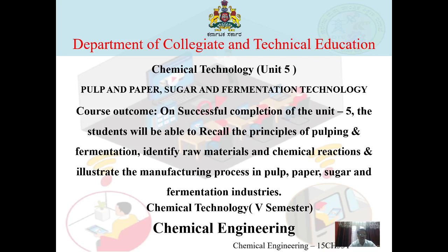In this process, sulfur is melted in a tank heated by rotary burners. Sulfur vapors are burnt in the combustion chamber to sulfur dioxide with controlled oxygen, to avoid the formation of sulfur trioxide.